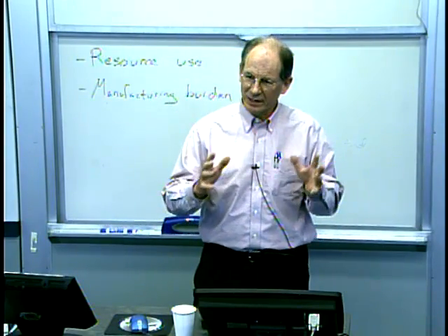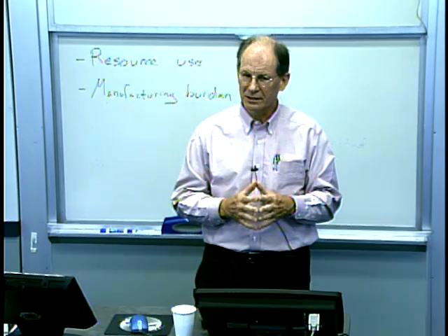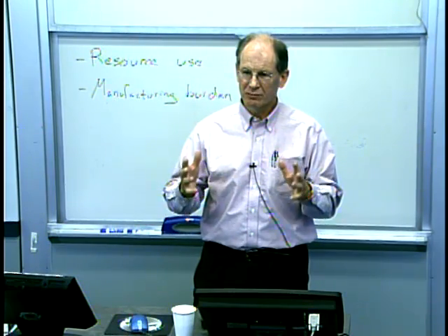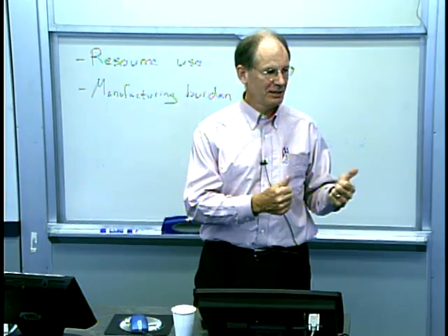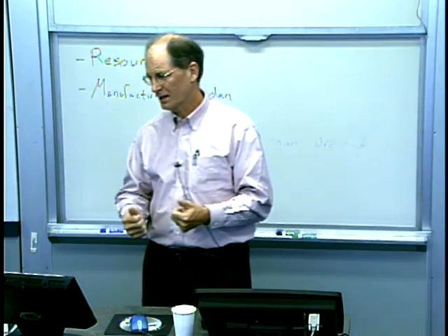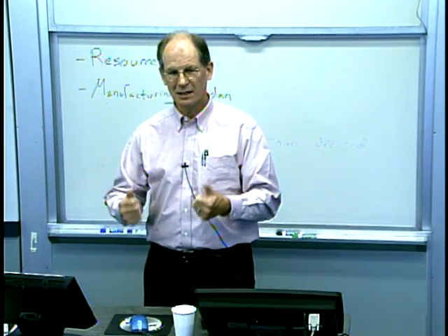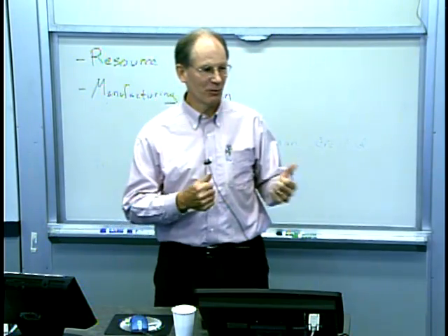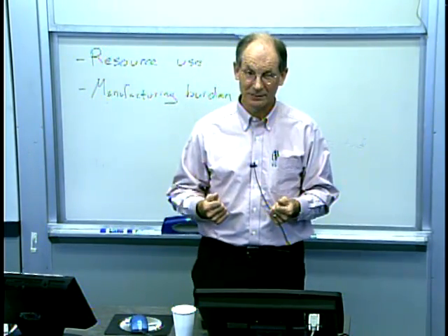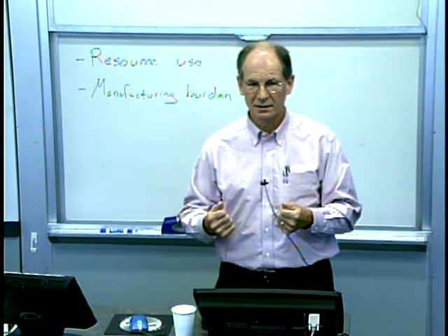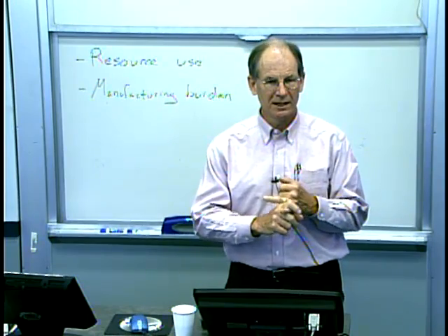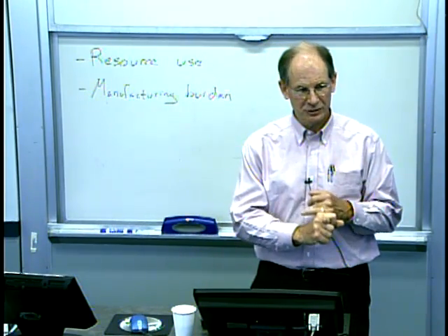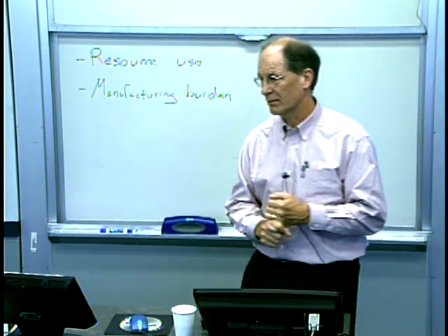And so that kind of led to this idea of statistical process control, which is really based on the idea that if I do everything I can to know everything I can about a process, then the only thing that's left is that unknowable part, if you will, the purely random part. And at one level, SPC is all about, first of all, determining, have I indeed taken care of all those things that I should know about or could know about?